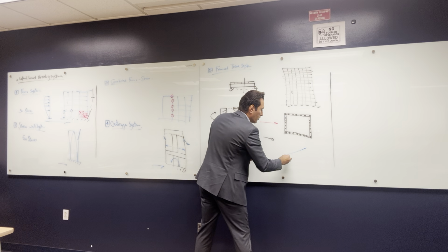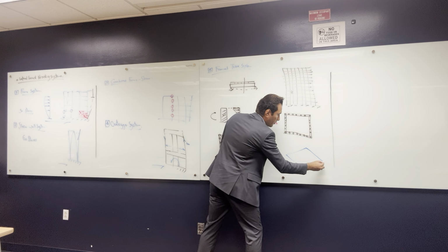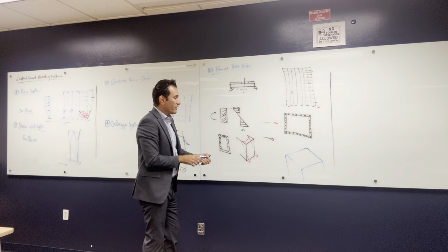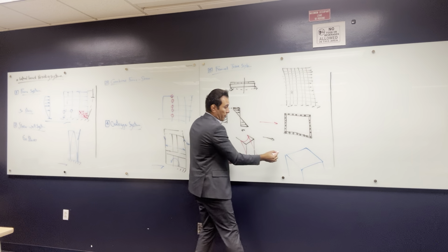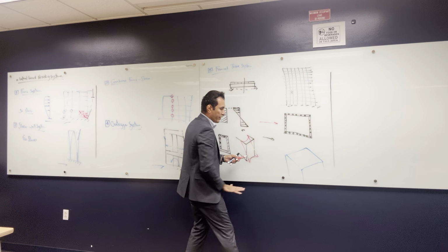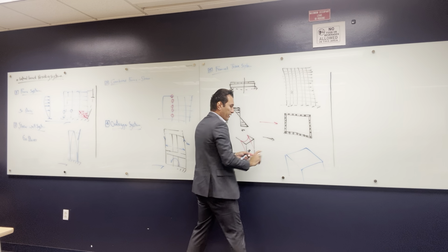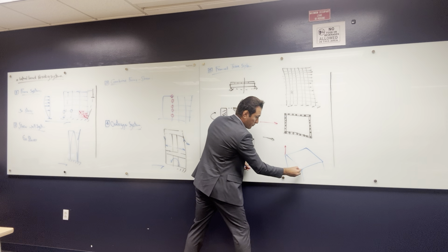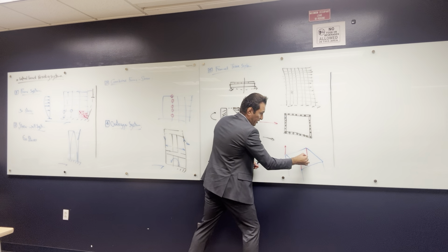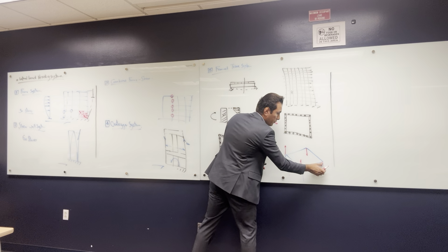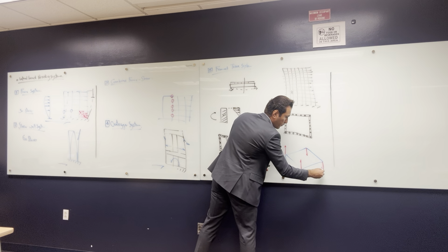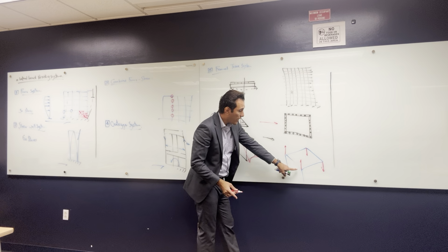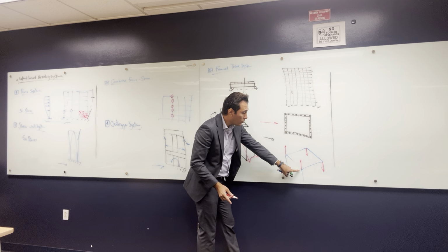Here is the building. Right? So what is going to happen? When an earthquake hits this building that way, it is going to have a bending that way. So all the columns here are going to have tension, and the other side is going to have compression, right? Like this. The thing is, these two are going to have the most stresses.